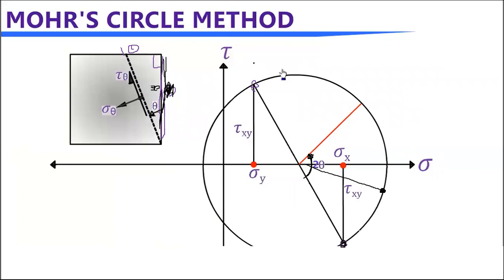Usually, when you have known points, let's say this is A, B, this is C, D. You know these points, right? You locate those points and you can take from simple geometry the center of the Mohr circle. The x coordinate is going to be a plus b over 2. It is from the geometry, right?